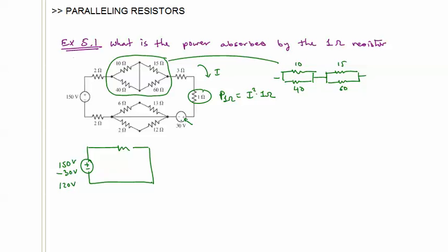It doesn't matter that the voltage source is here. It could have been placed here. It could have been placed anywhere around the loop, and it would still have contributed to a net effort, if you will, to push current I through the lumped amount of resistance that we have. This resistance, RE, is going to be equal to 2 ohms, plus this 3 ohms, plus the 1 ohm, plus the 2 ohms here.